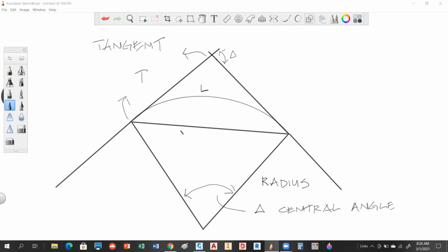So you have quite a few parameters, and you guys that'll be taking a route surveying course, you'll talk a lot about these, but I'm going to introduce them a little bit today because they're kind of important, because Civil 3D is going to talk to you in this term. So again, central angle, radius, distance, which these two things are known pretty much the most. You don't normally design around an L. You don't normally design around a chord. Some people use T, but these are the most common right here.